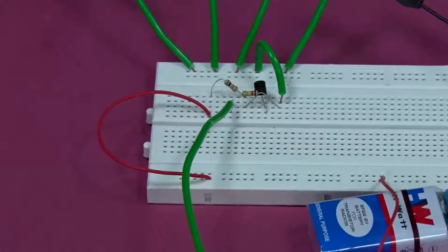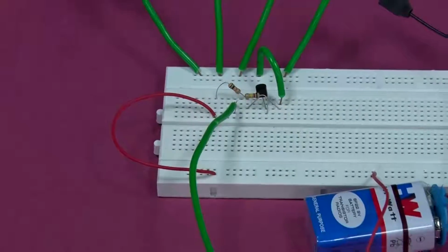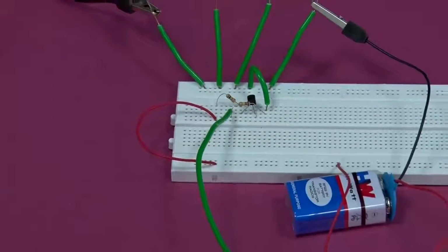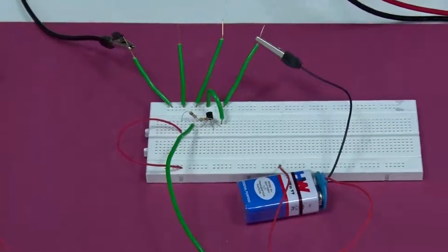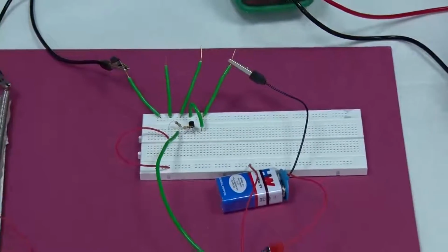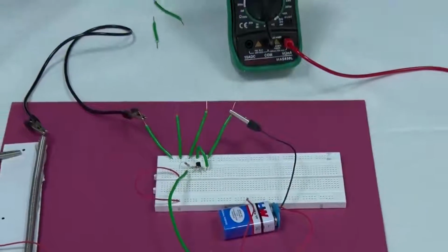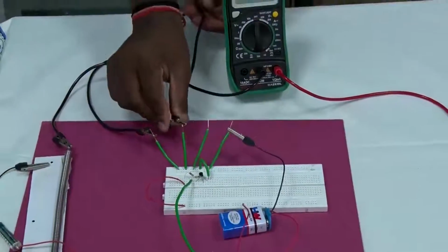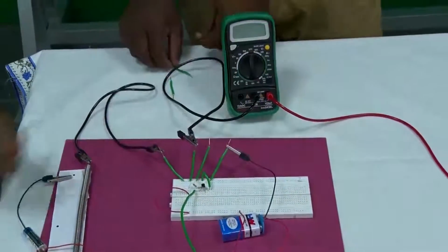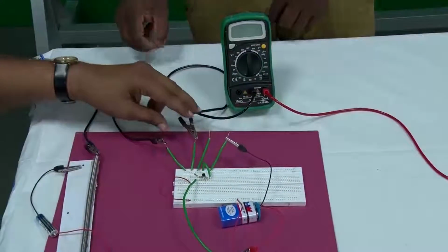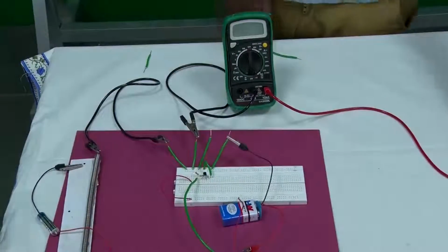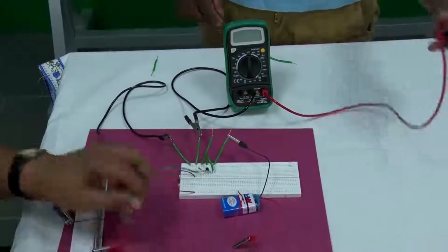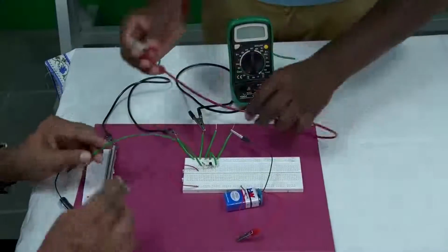Now, we have to add the multimeters for measurements. So, one multimeter is needed for that input side. The black terminal should go to the ground 0. Yeah, the black terminal is going to 0, good. And then the red one should go to that variable point. Where is that variable point? Here. So, that red terminal should be connected here.